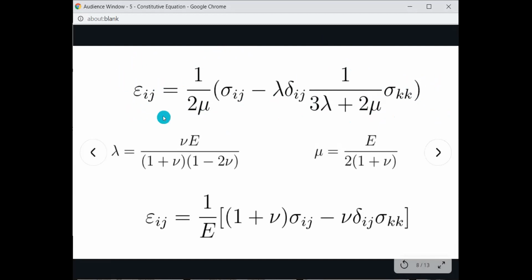So in experiments, what they got is E, which is the modulus of elasticity, and nu, which is the Poisson's ratio. So ano yung modulus of elasticity? That is the slope. Okay, so balik tayo doon sa stress strain curve, pero hanggang sa linear lang tayo. That is the slope of the elastic part or the linear proportional part of the stress strain curve. So that is the E, or the modulus of elasticity, also known as the Young's modulus.